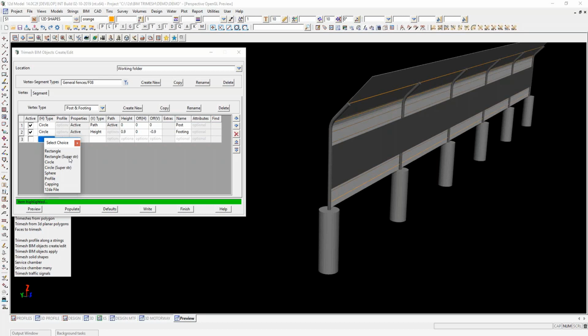So you've got the choice between either making a trimesh straight away, or making a particular part of the structure a superstring. When these things go across to IFC, the superstring gets converted to a trimesh anyway. So that's the shapes you have, the choices.